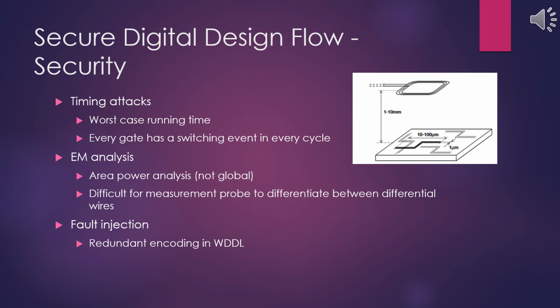The design is also resistant to fault injection attacks due to the redundant encoding in WDDL cells. Each state is represented by 2 bits, so error detection is possible.